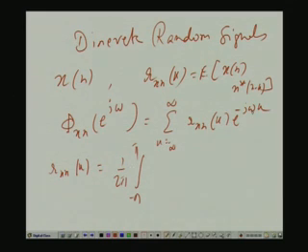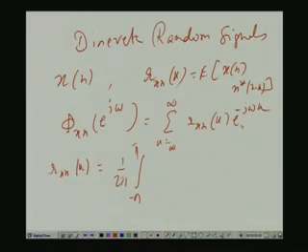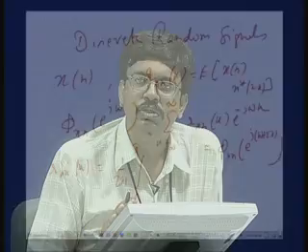And one more thing, if instead of omega, you replace omega by, say, omega plus 2 pi, what do I get? I get one term as e to the power minus j omega k as it is, and another term e to the power minus j 2 pi k. Now, e to the power j 2 pi k or e to the power minus j 2 pi k is always 1. That is, if you take any angle 2 pi and any integral multiple of that in the positive or negative direction, e to the power of that is always 1. E to the power j 2 pi is 1, e to the power j 4 pi is 1, e to the power j 6 pi is 1, e to the power minus j 2 pi is 1, and so forth. So, if you replace omega by omega plus 2 pi, you still get the same expression. That is, this is the same as e to the power j omega plus 2 pi. If that be so, this function is a periodic function of omega over a period 2 pi. So, it is enough that we plot it from 0 to 2 pi or minus pi to pi. I prefer minus pi to pi, and whatever you see there just gets repeated. Okay. These are all facts from DSP, but in case you do not know, it is worth mentioning here.